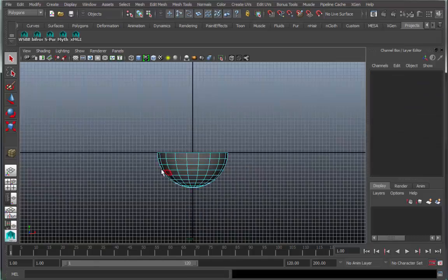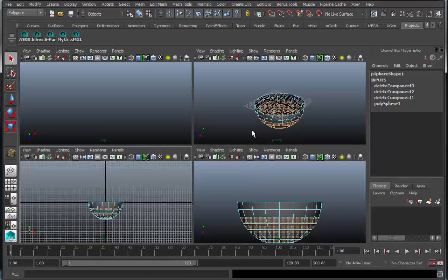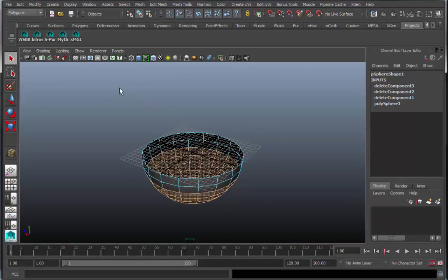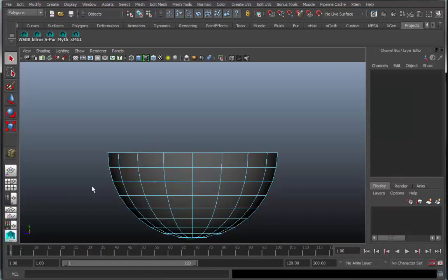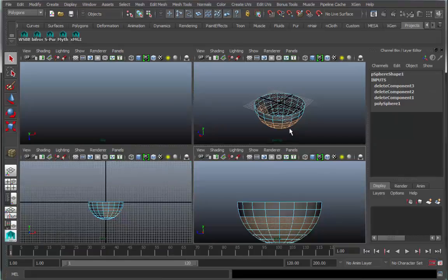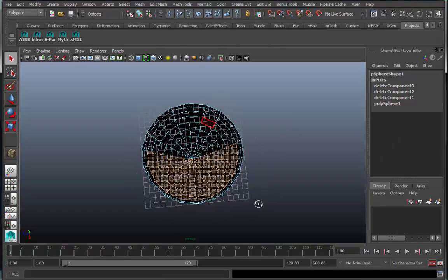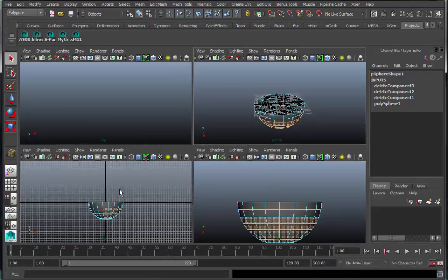But what this does allow us is the ability to grab faces, and suddenly we're grabbing all the way through, because now our camera includes the view shot out to include everything, not just the front, but also the back. You can see that by having the grid as well. So this camera here is not really fixed, and it's only grabbing, as you see, half of the polygons, i.e. the ones that face us. This view, the side view, has everything, meaning that we have the grid in it because we've pushed back the camera's view. So now we're able to grab everything in the front and back.